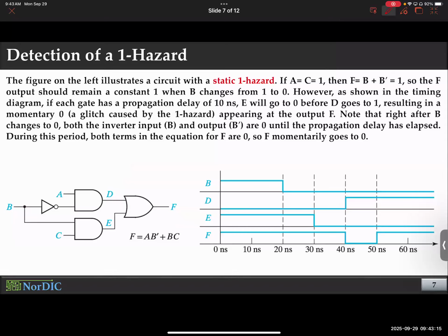So this is 10 nanosecond, this is 10 nanoseconds, so 20 nanosecond. Why is that? Can anybody tell me? Yes. Thank you. Yes, perfect. So notice the signal B, it's traveling through 1 and 2 gates. And we are oversimplifying it, honestly. Every logic gate has different level of delay. Inverter delay will never be the same as AND gate delay. But this is for the sake of our understanding. So 10 and 10, 20 nanosecond. That's why you see that it is 20 nanosecond delayed because it went through two logic gates.